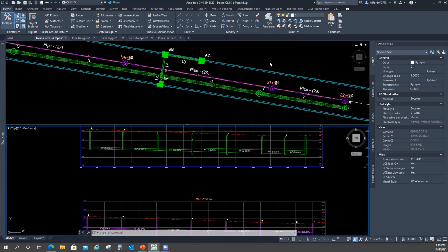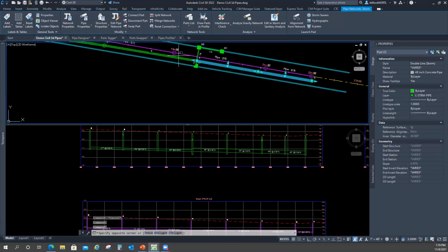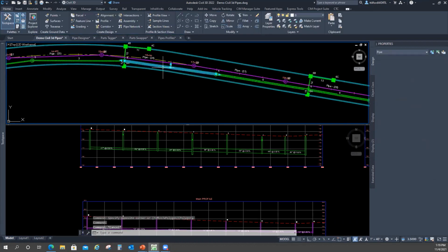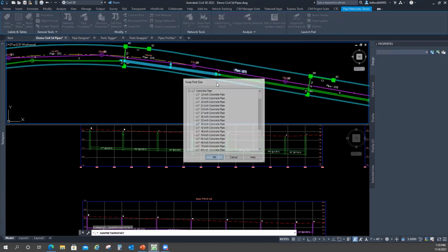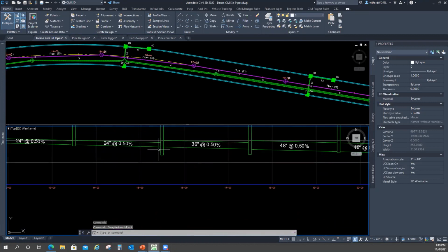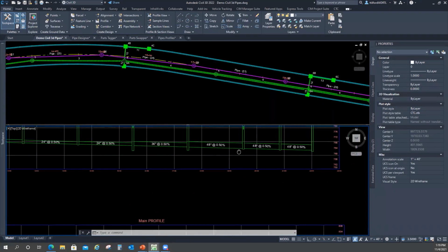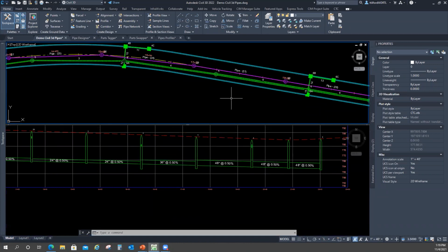What about swapping out parts? We just talked about it. Say the engineer wants all these pipes to be 36 inches. If I swap this part out for a 36 inch, that means this slope's going to change. And once I start coming down this road, these are going to start to be 0. And I'm going to have to edit this run over again at that 0.4 or 0.5% slope as I swap out parts. So that's where the tedious is in Civil 3D.